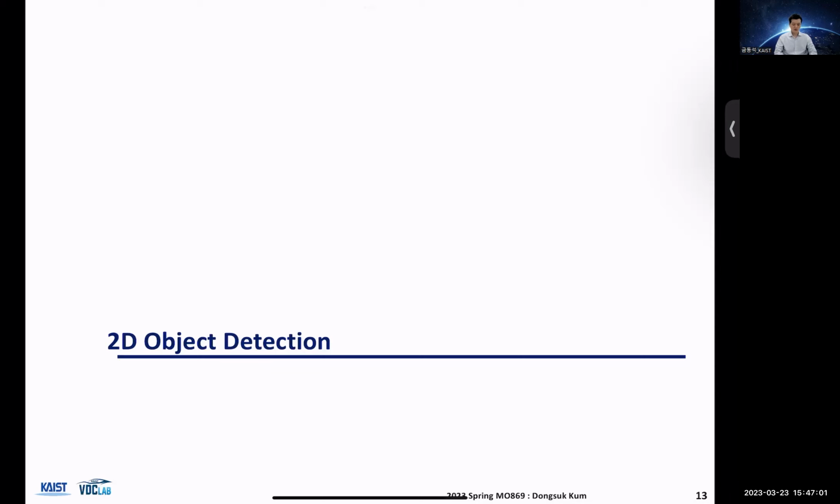All right, so that gives you the camera model, camera intrinsic, and extrinsic parameter. When you put your cameras on a vehicle, you will need to do camera calibration, which means that you need to understand the internal parameters of the camera itself and where it's mounted, which corresponds to the extrinsic parameter. Now let's talk about the detection and perception tasks. Now it's all about deep learning.